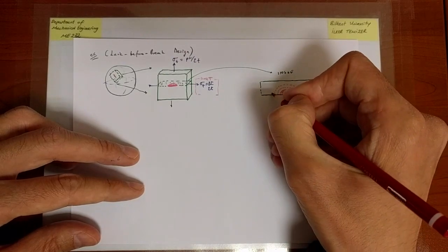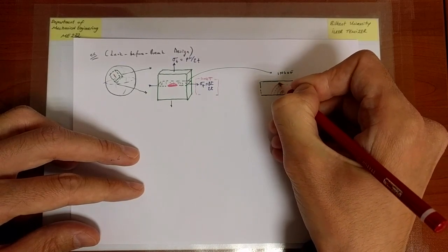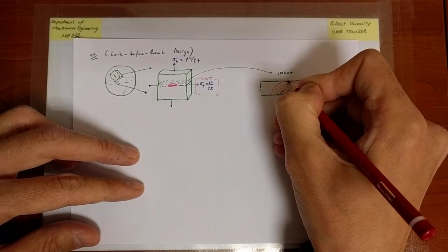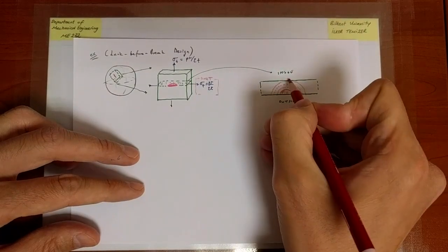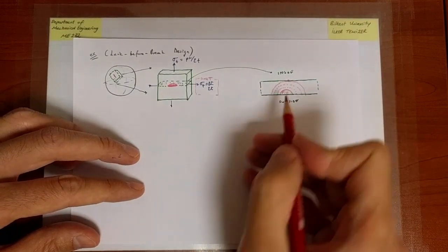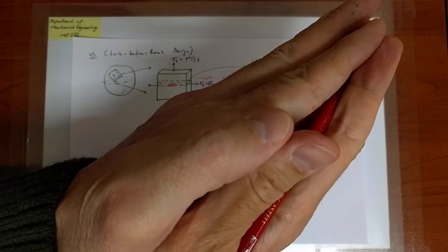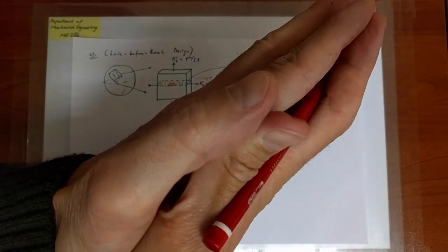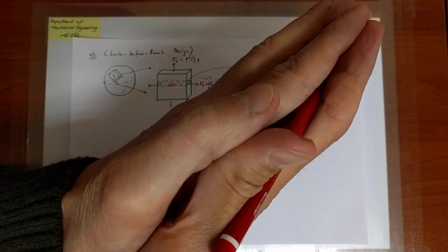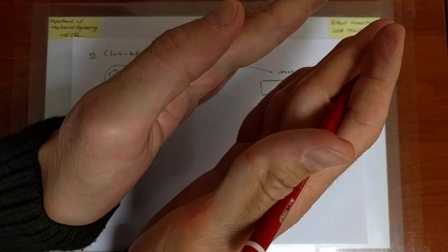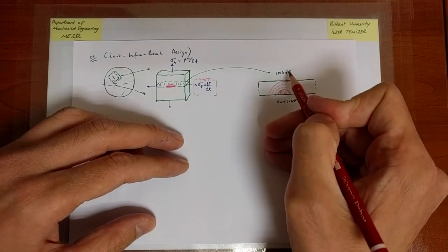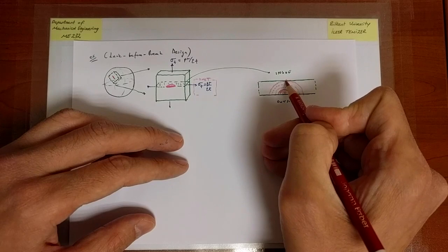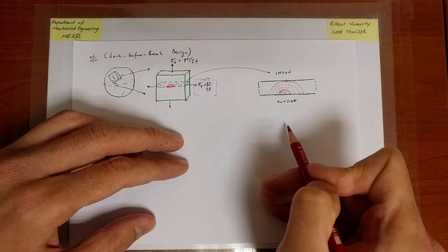What can happen is that this crack can ultimately hit the inner surface of the vessel, and as soon as it hits it, well, a crack has two surfaces that are freely movable away from each other, so there is a tiny but certainly a certain amount of gap between them. So as soon as it hits the surface, the pressurized gas inside will leak through the crack to the outside.